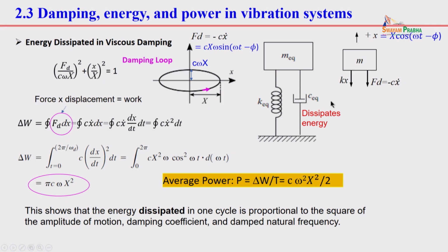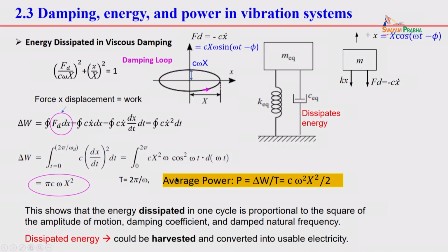It's a trade-off. So the total energy that can be harvested is related to the damper C. Then damping is very important. It doesn't mean that if we increase damping, we have more power, because the amplitude decreases.